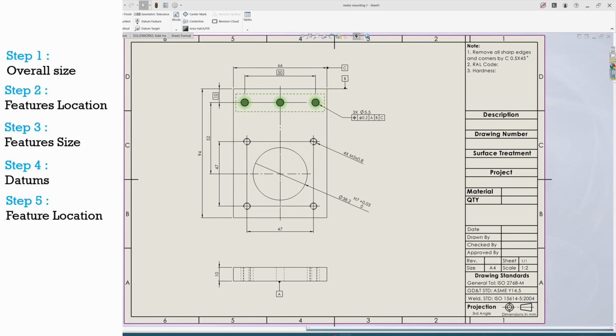So as there are 3 holes and these are in a pattern, I have defined the pattern position tolerance. And I also added the material conditions over the datum. We call it datum shift. But I want you to ignore this material condition and this pattern tolerance as of now. In this video, I want you to only understand that we have defined the position intent of this hole.